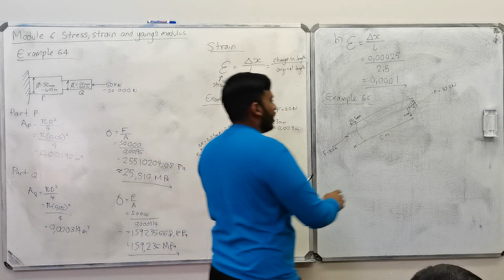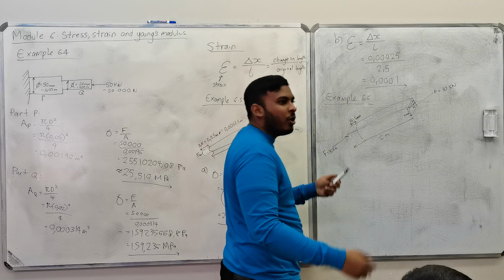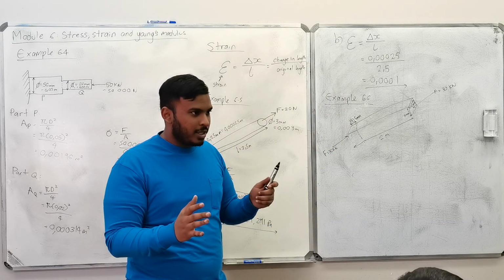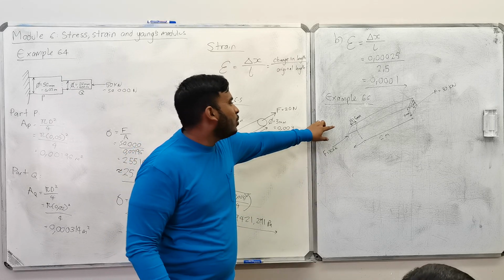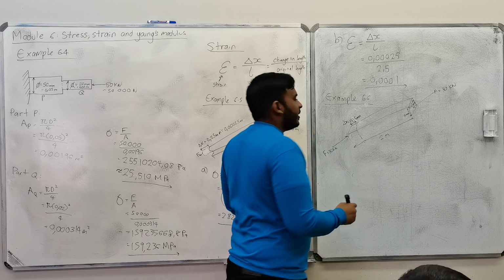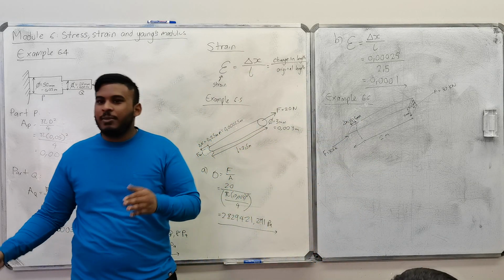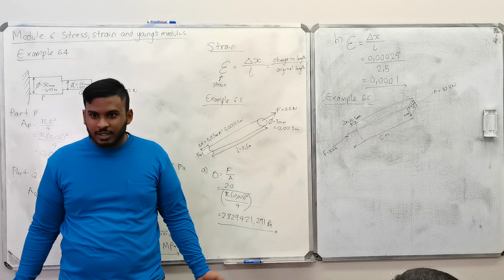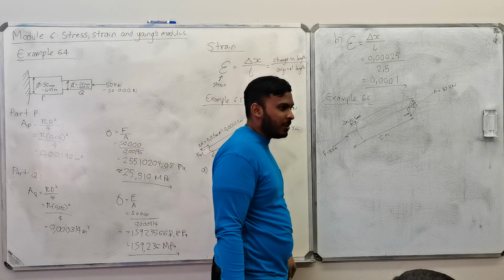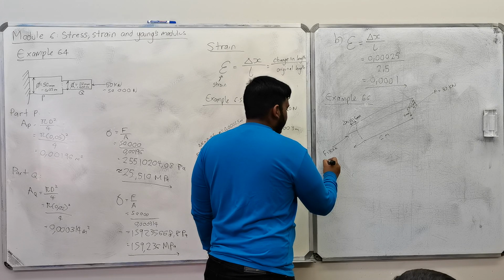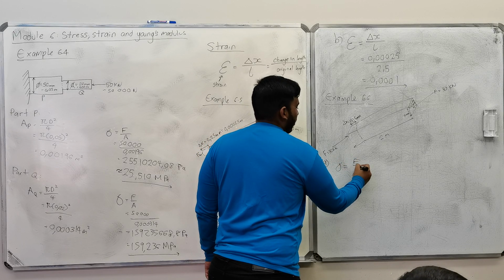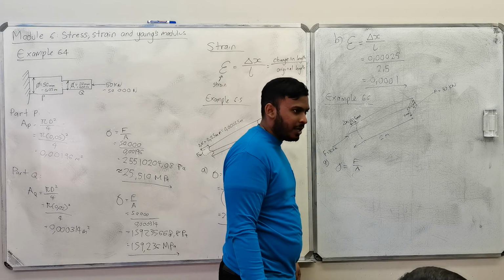So remember, with compressive force, that's the information, right? Your bar was originally 2 meters long. With compressive force, you're basically squashing it, so the bar is going to come out shorter. They basically told you that it now became 0.35 millimeters shorter than what it was. So they want to know the stress, compressive forces being applied. Stress is equal to force all over area, right?